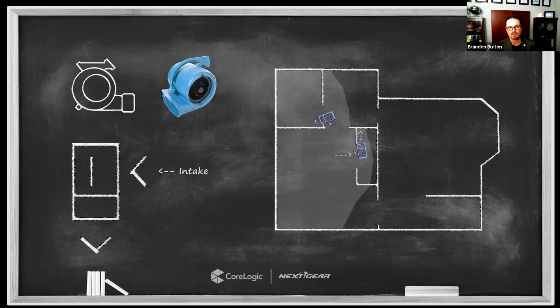At this opening between this larger affected room and the closet, I'm going to install that air mover so that it draws from the larger room and then forces that air into the smaller closet. Again, creating an air exchange between these two adjoining affected areas. Now I'm going to pause there for a minute.